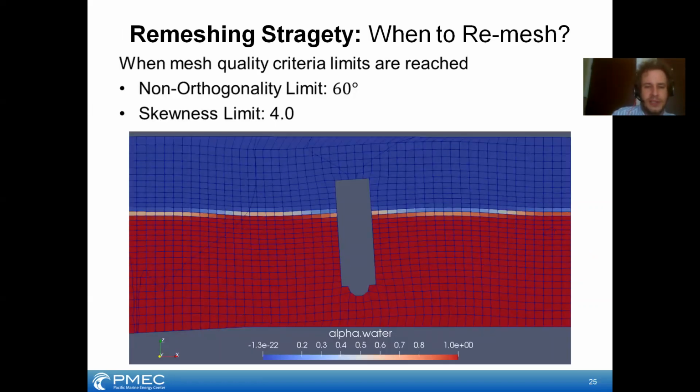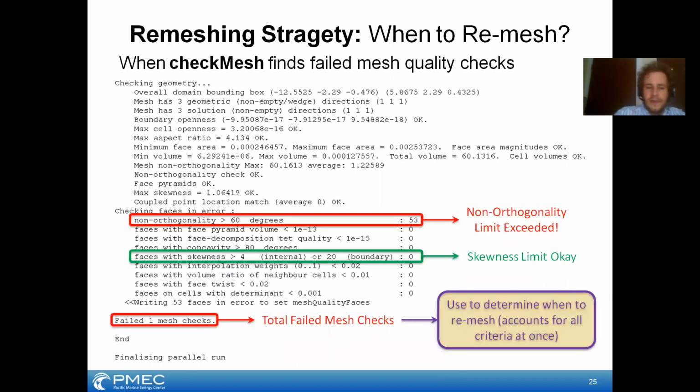And these were very conservative parameters to keep the fluid solution running very nicely, smooth and stable, since the rigid body motion part is actually the most unstable. So we wanted to keep a good fluid solution going first to help maintain stability of the whole process as much as possible. And so when you run the check mesh utility, you get an output that's very long,